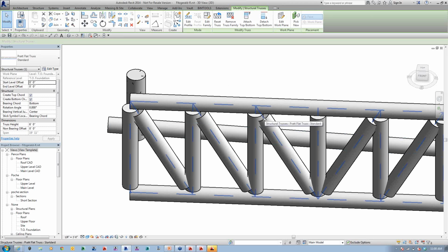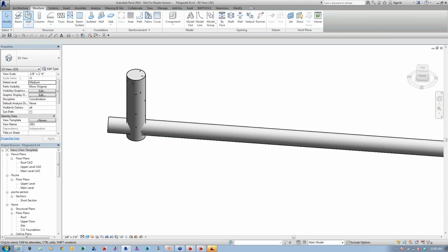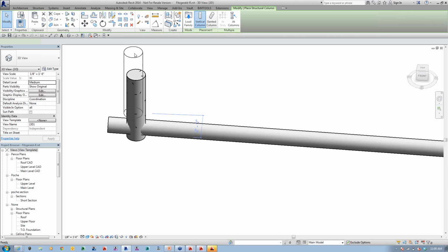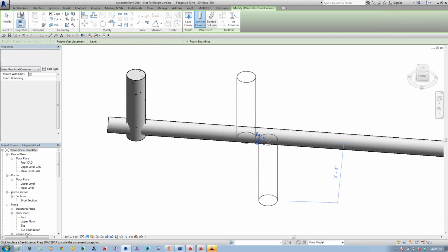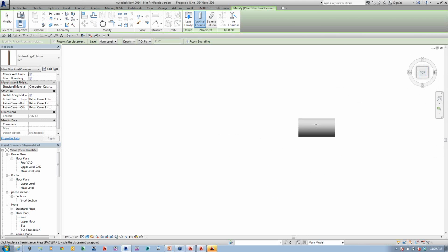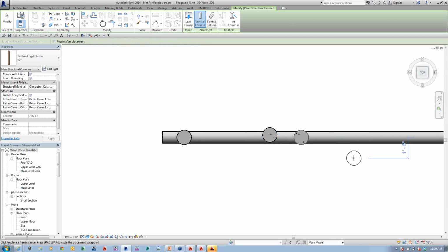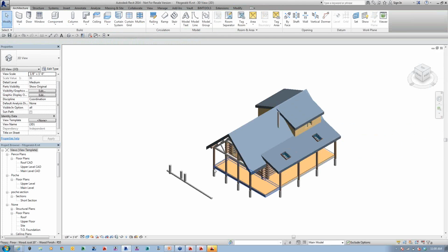It just drives me nuts trying to get all this to work out in here. So instead, I start building in combinations, and a lot of times I'll use a regular wood column, an architectural column, for this, because the two just ignore each other as far as what they're doing, and they never really clean up inside. So you can put these inside each other all day. They don't try to clean up and do weird things.